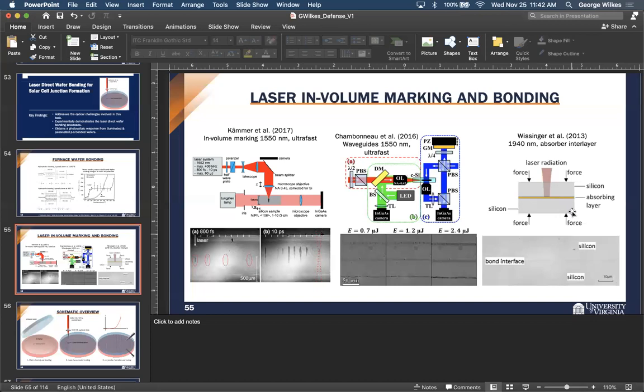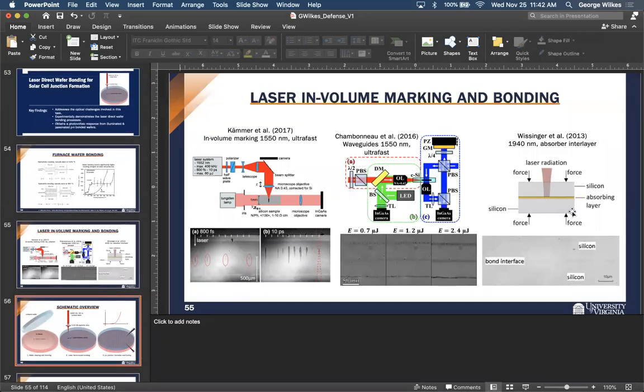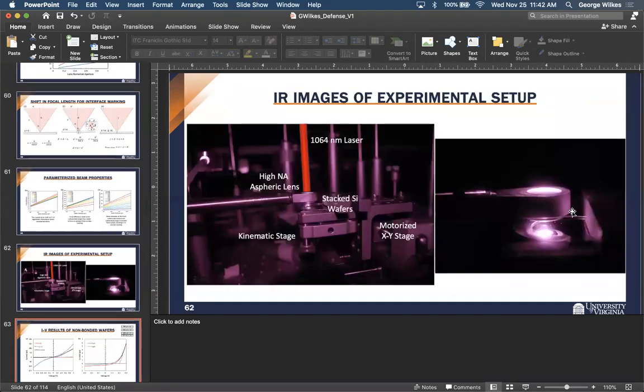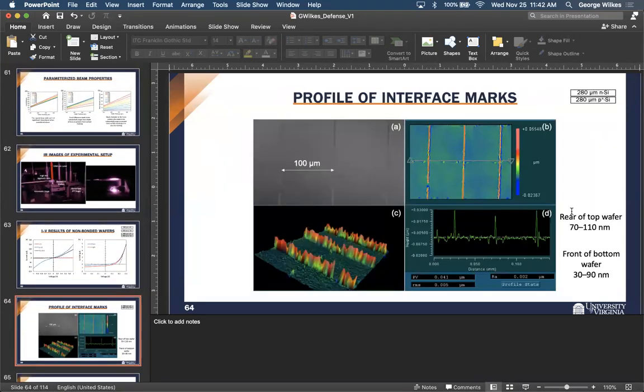Okay. I was wondering if you actually need to bond the surface, well, both surfaces completely. I think what you did was line by line, spinning the laser. So that gives mechanical strength, or makes the mechanical bond, right, so that the two wafers stick together. Are those the only regions where you may actually form a p-n junction, or what's between these lines going on? I'm not sure what the expectation is. I guess there could just be air gaps there, which obviously is not good.